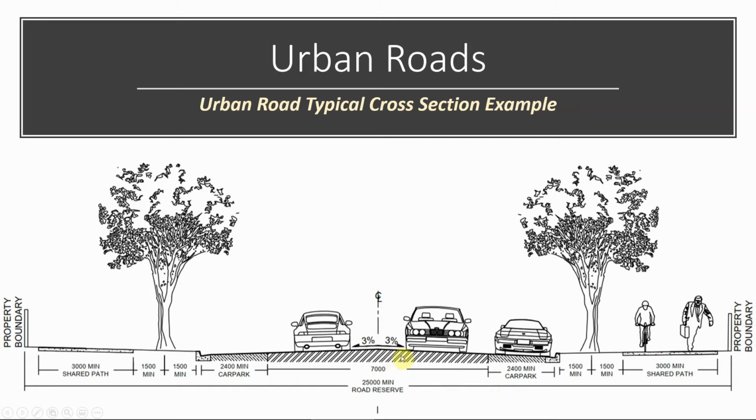Instead, for our road, we will look for a 3.6 wide lane each side rather than 3.5. We will not have that car park space, and we will have the urban curb and gutter. We will have that area for planting trees. We call it boulevard. Rather than having it 3 meters wide, we will have 1500 wide, and we will have the sidewalk. And rather than having that as 3 meters wide, we will have just 1.5 meters wide, and we will have another small gap there, or another boulevard, an external boulevard of 300 millimeters on the outside.